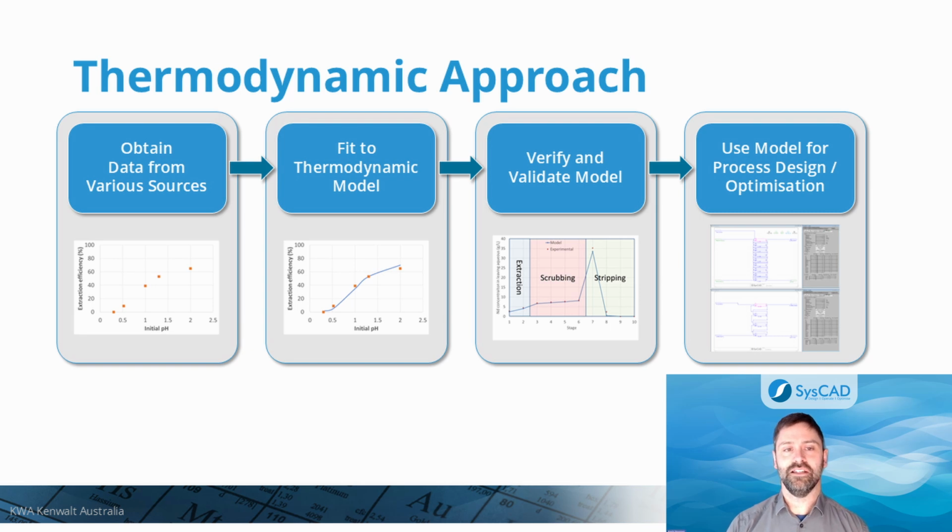The approach taken in this work is illustrated in this slide. Firstly, data from open literature sources was gathered. After this, a thermodynamic model of the organic aqueous exchange mechanism was developed. Using the SciPy Optimize package in Python, a SysCAD model of a shakeout test was repeatedly run using various equilibrium constants for the ion exchange reactions, until error between model predictions and experimental data was minimized.